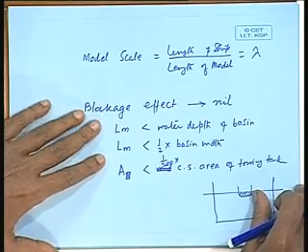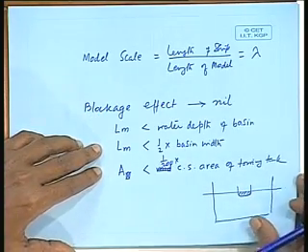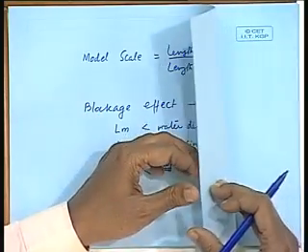If I cannot achieve this, then I should make some blockage correction. There is a number of literature available in standard textbooks on resistance, which give the references of literature on blockage correction, that can be used.